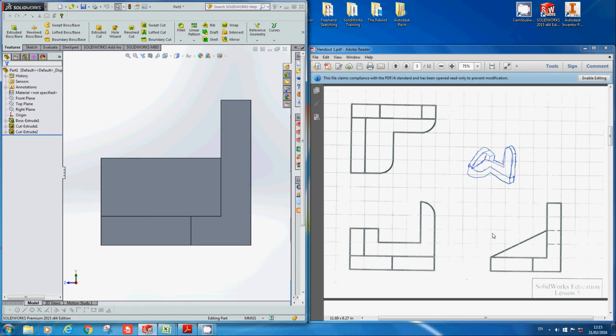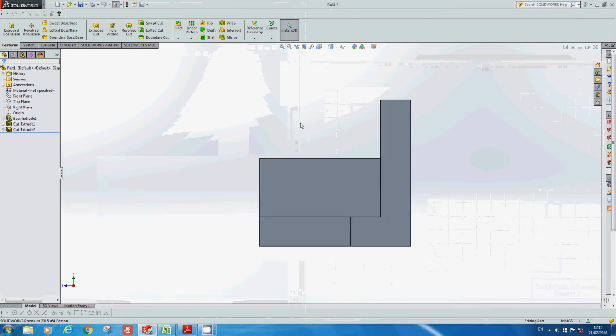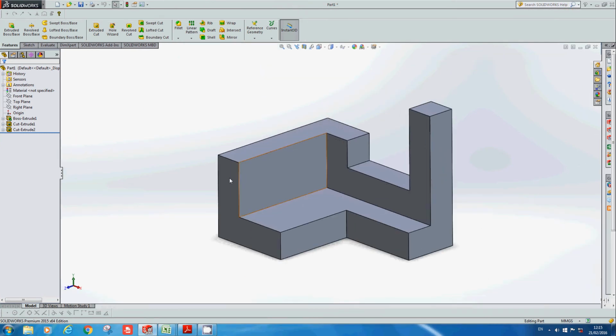We're going to use a chamfer, but it's going to be a distance chamfer as opposed to the distance angle chamfer we're used to. So we'll apply this chamfer next. So just hit maximize there again. So I know it's this edge I need to apply it to. So if I come up here to the top to the commands, click the drop down and select chamfer.